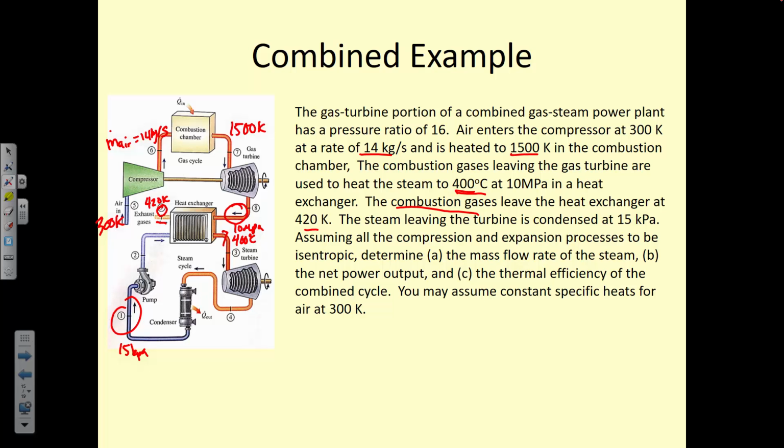My question was, how is it heating the water then to 673 Kelvin when the steam leaves it, because it's coming in at 1500? Well, it's not coming in at 1500, you're right, it's coming in at higher. So if it were not a cross-flow heat exchanger, it couldn't do that. If it was parallel flow, but cross-flow, it can do that, because it's coming in hotter here. Good question, though. That's okay. I do weird things all the time, so sometimes I make mistakes.